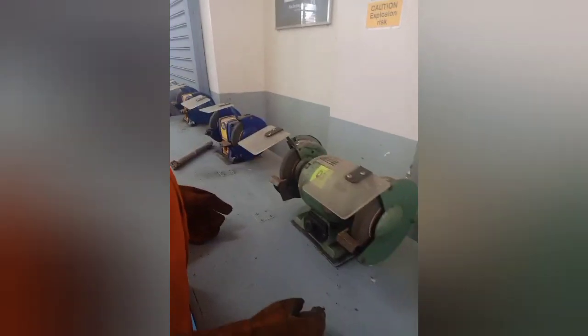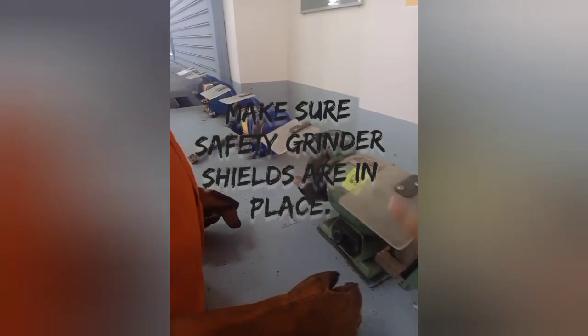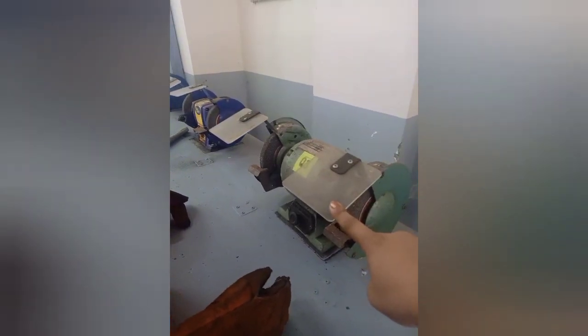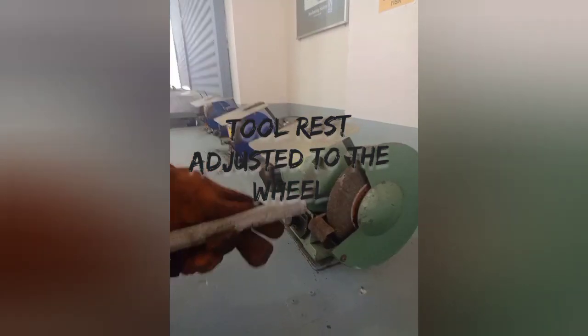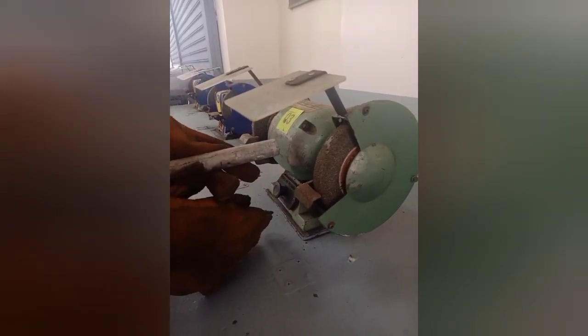Always keep your hands away from the wheel. Make sure the grinder shields are in place, and keep the tool rest adjusted close to the wheel.